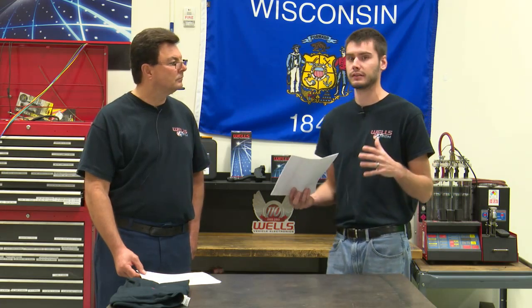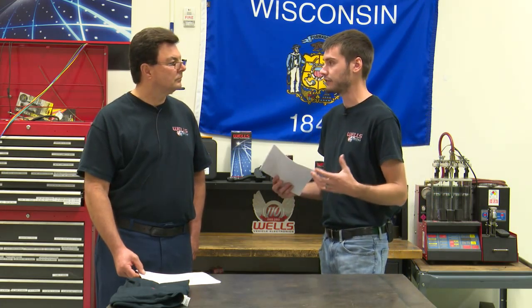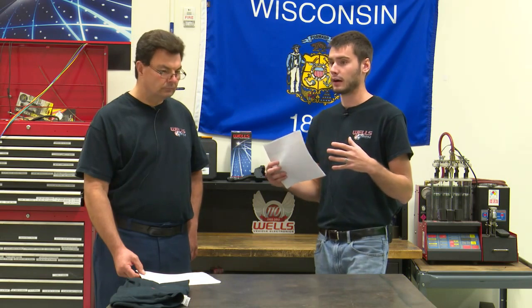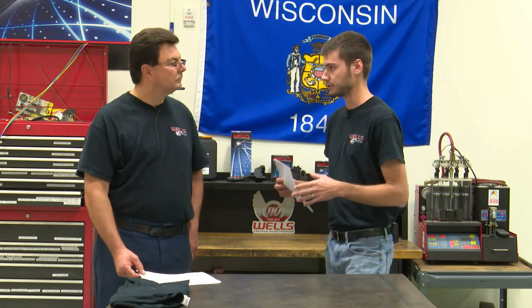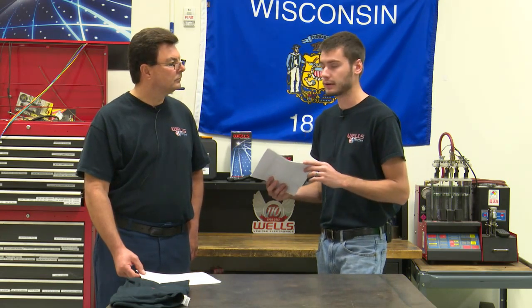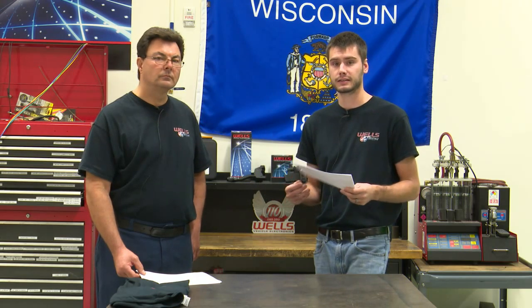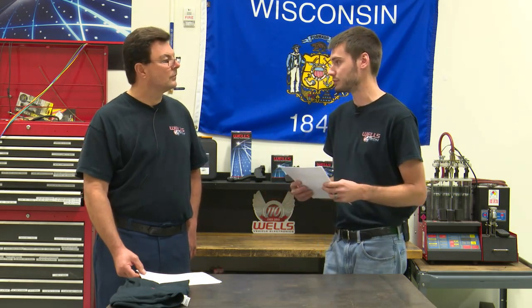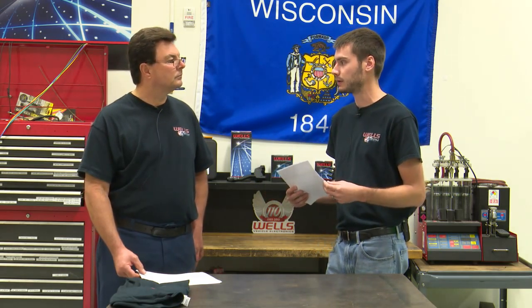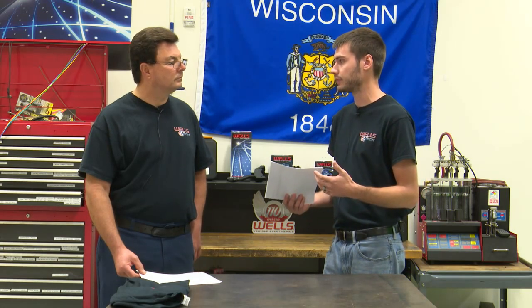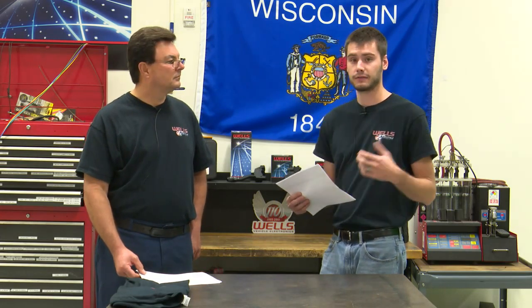All manufacturers selling vehicles in the United States have to have those mandated trouble codes. Okay, so they're always going to be the same. That's why, working in the business for a long time, a lot of technicians are able to memorize those codes because they come up so often. OBD1 guys, that was easier when they only had a few codes. That's right. Now we're moving into the thousands of codes on newer cars, and then they get into manufacturer specific.